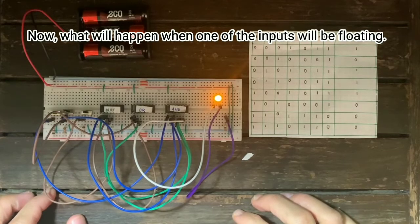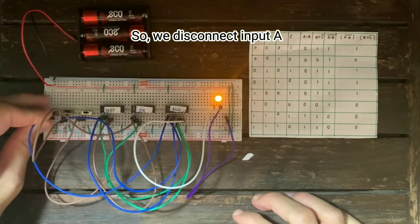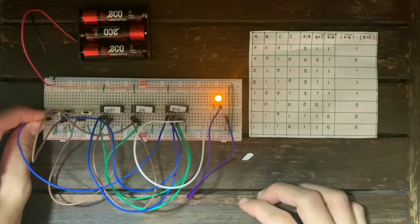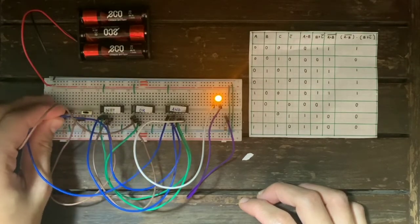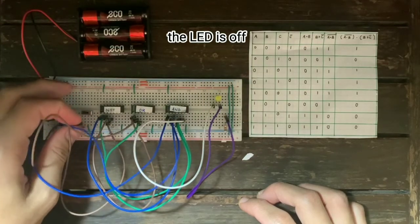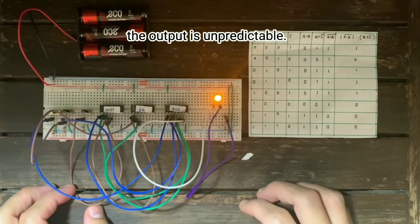Now, what will happen when one of the inputs is floating? So we disconnect input A, the LED is still on. When we disconnect input B, the LED is still on. When we disconnect input C, the LED is off. So this proves that when floating happens, the output is unpredictable.